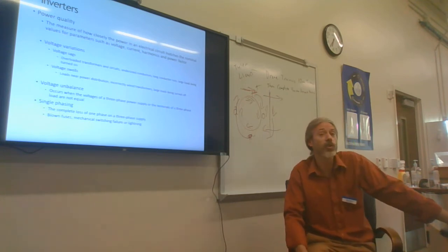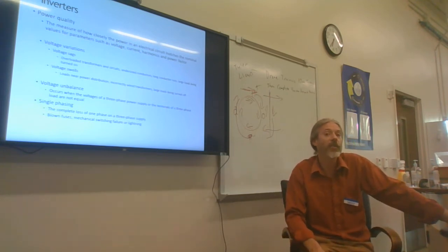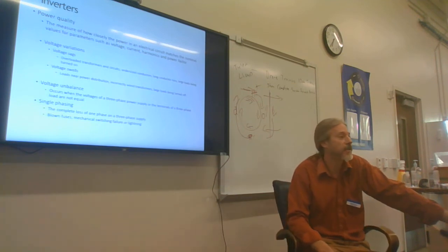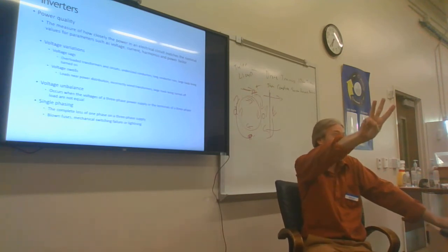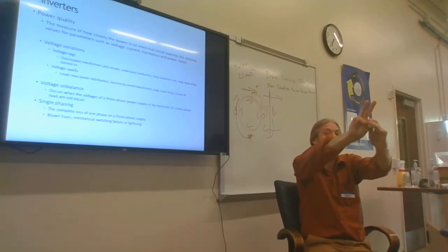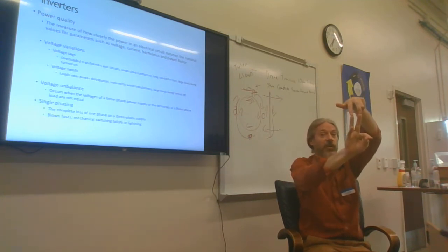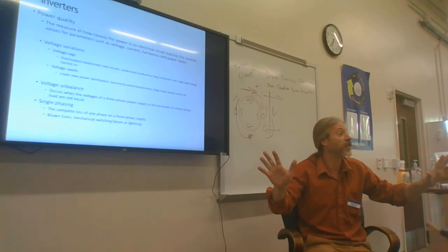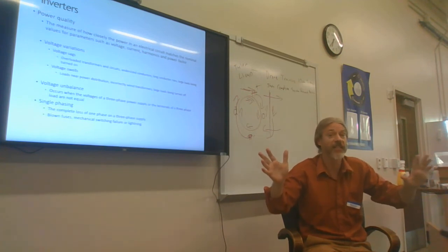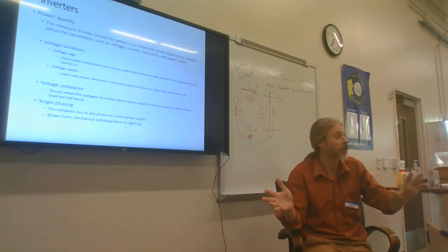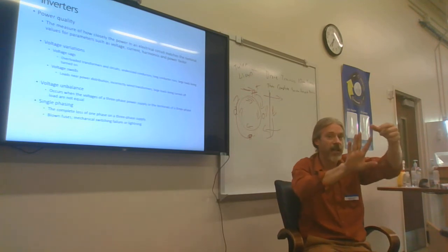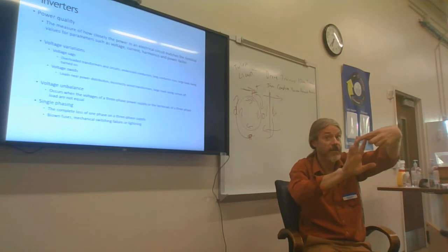If you ever lose one of the 3 phases, you now have 2 phases, right? No. Remember, I have 3 wires. As soon as I lose one, I only have 1 phase, the phase between these 2. There is no such thing as 2 phase. It can't exist in a safe environment. Okay? To have 2 different phases, I'm going to have a 3rd wire. If I have 3 wires, then I have 3 phases.